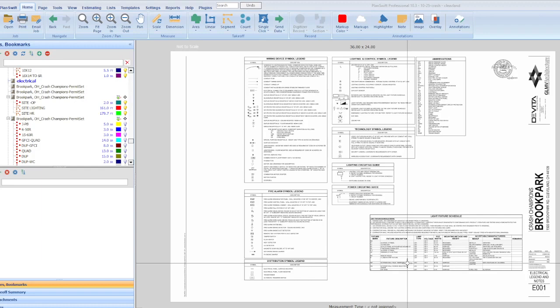And in the neatest way you can, because an electrician is not just going to throw the wire all over the ceiling. Everything that's going to one panel, you'll probably run all together and gather it on one side of the building. If another panel is in the middle of the building, then you're going to route everything towards that way. So that helps too.